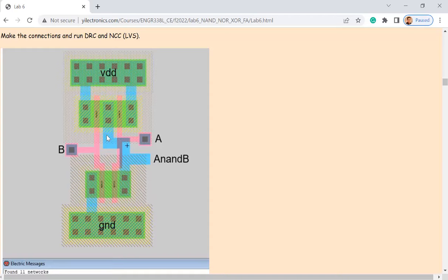So I think what I did in the larger scale design is, the reason that I cannot place this one here is because this is a poly to metal 1 via, so it has both poly and metal 1 material in there. Because I want to make the gate compact, I don't have much space.